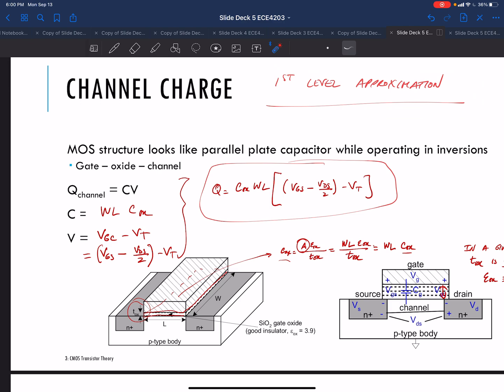If you look at the SPICE models we'll use to simulate later, a typical SPICE model for processes like 0.18 micron is a level 49, and things didn't stop at level 49. This is even pretty old, circa a 0.18 micron or 180 nanometer process.